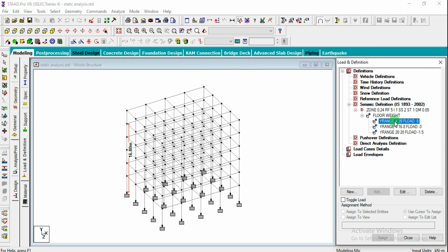So this is dead load, as it is, whatever value we have to assign there. And the second and third ones are live loads. Okay, and for live load, which we are going to define in the seismic definition, we have to take 50%. So we have defined half of the pressure values there. And next step, we need to create the load case details here.